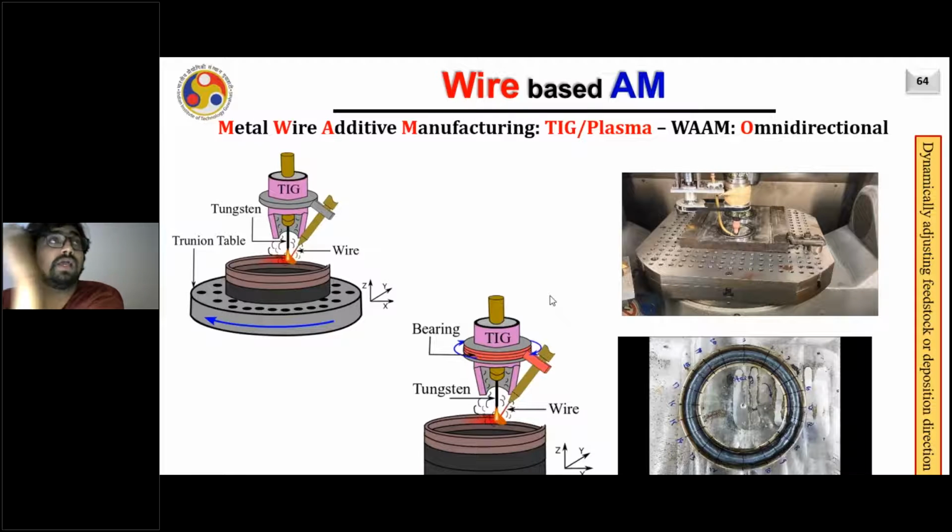If you really want to build something useful, you need to be more careful in the case of TIG, because here you want to make sure whether your wire is appropriately rotating around the melt pool or not, right? Otherwise, you have to make some auxiliary arrangements with the system in such a way that only then it will be possible to deposit the material appropriately.